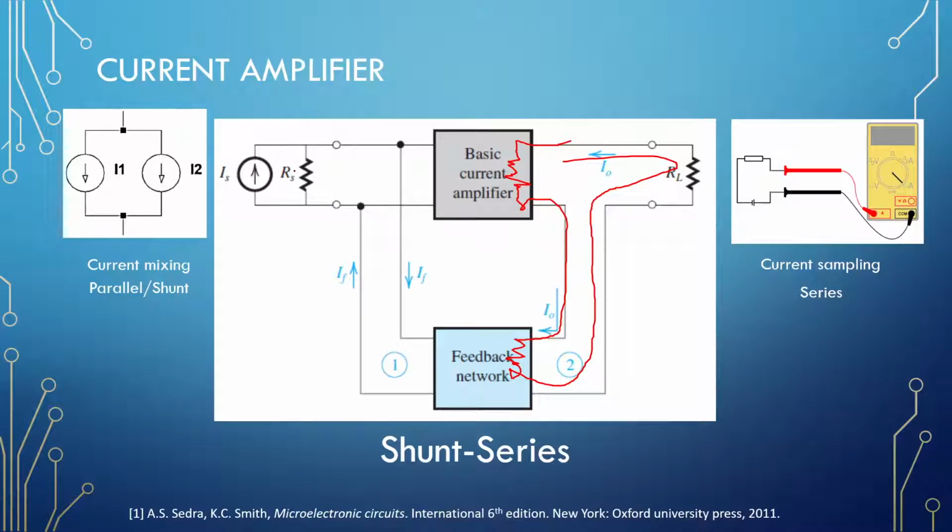So current source should have a resistor in parallel with it, Norton. The input resistor here will be in parallel with this one. The output impedance of a feedback network will be in parallel with everything here. So the input impedance, everything will be in parallel, and the summing of currents also happens in parallel or in shunt.